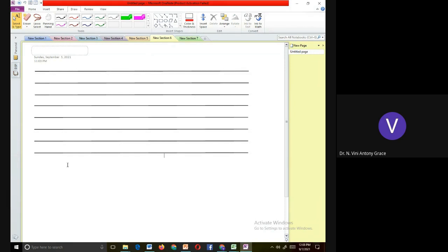Draw 8 lines like this. Start with the 8-point DFT computation first. Write the input as such. Input is in normal order. Write it as such: 2 2 2 2 1 1 1 1. Draw the butterfly structure for the 8-point DFT. Initially there should be the butterfly, and then the phase factors have to be mentioned. So draw the butterfly structure carefully.